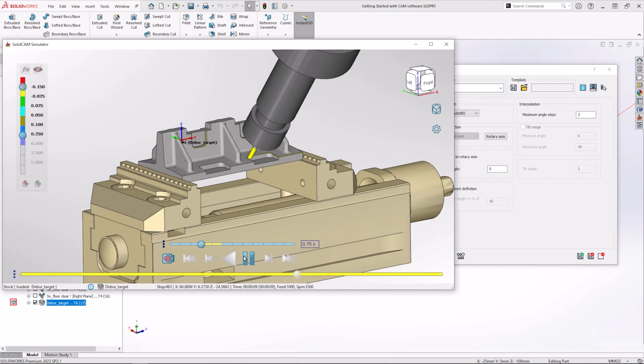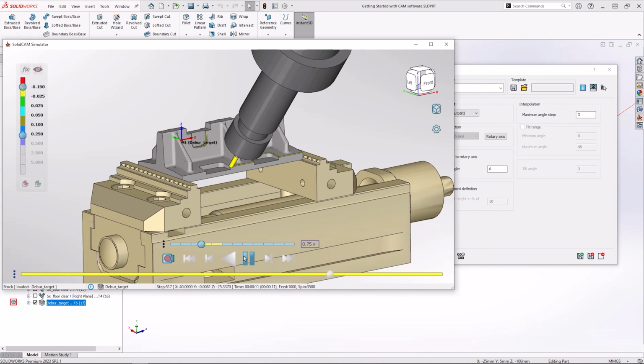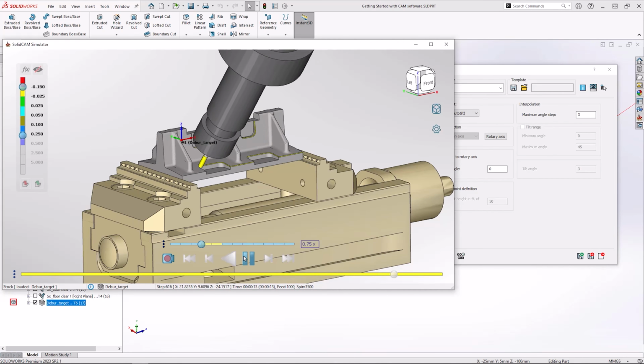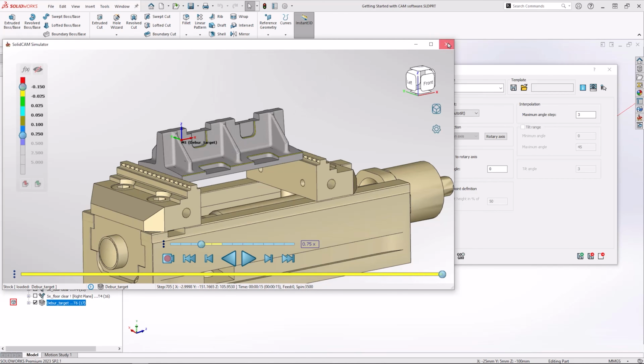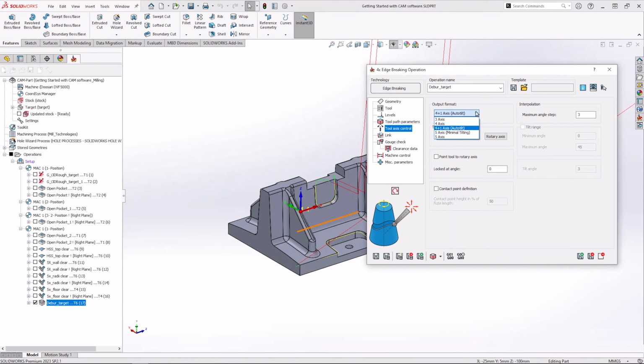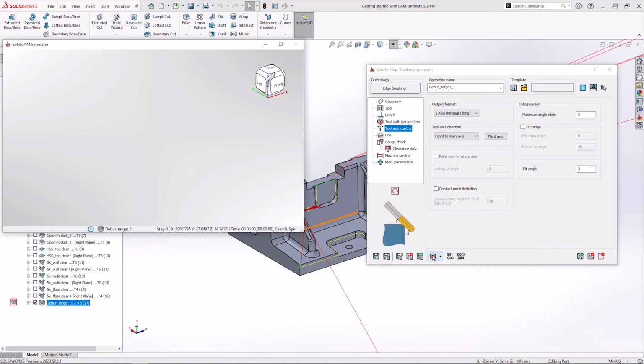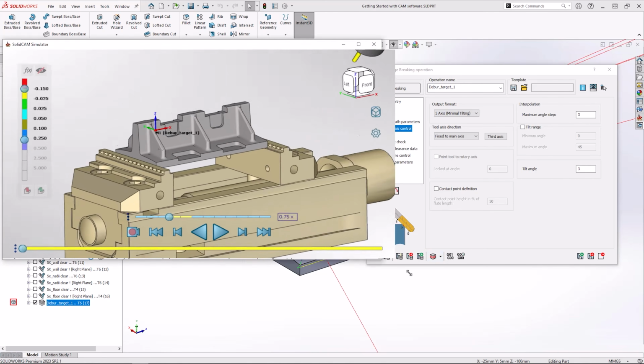So to recap, what we've seen is one of the rotary axes is being kept static, and then the second will rotate slightly, so you can see that in the X direction, if that's what we've picked. Another option that's similar but with slightly different results is 5-axis minimal tilting. The difference with this one is we don't have to pick a preferential axis because it can use all 5 at the same time. It will still try and minimise the tilt used though, so you only should be moving absolutely when it's necessary.